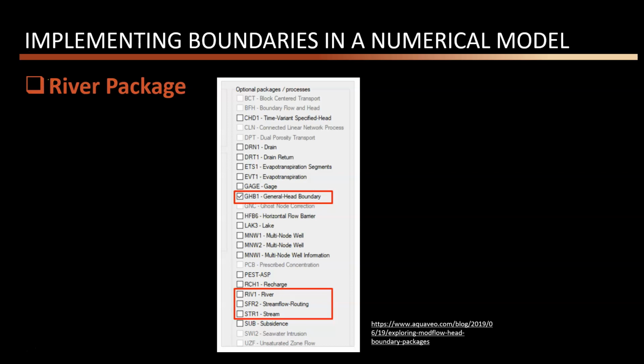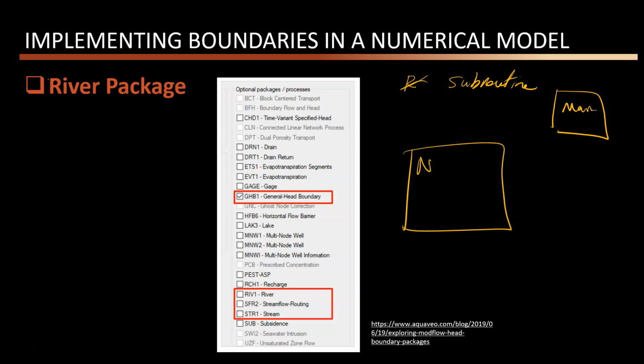You may wonder what the term package means, that I use a lot in this video, and I'm sure that you've already heard this. The packages are like the subroutines that we created for our main code. For example, here the main code is MODFLOW, which can solve the partial differential equation and find the H information for us. But these packages are developed by different people, and they created, for example, a well package which can simulate the well and provides the information which MODFLOW needs, and helps us to better simulate the impacts of the well.